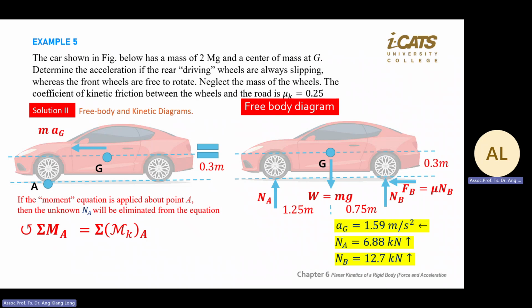So this is a second solution where you only focus on moment. If the question forces you to use the second method, you will see the question mention, by applying the moment equation, solve something. Meaning you are forced to use the moment in the free body diagram equal to the moment created by ma.